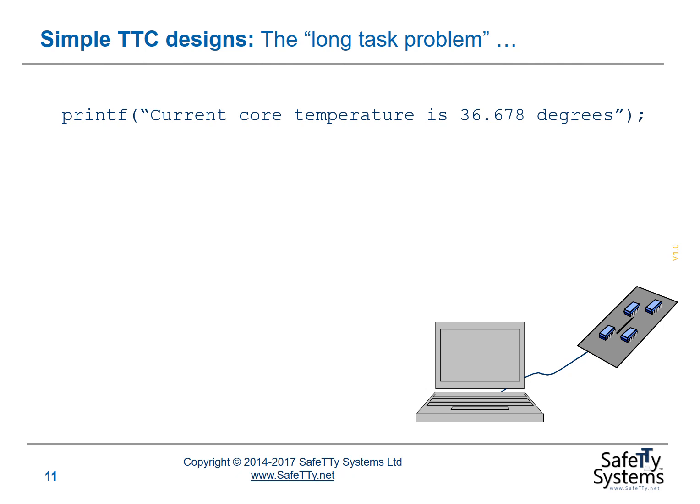So this is what I'm going to send. I'm going to use a printf function that is provided by my compiler manufacturer, I'm assuming, to send this string of characters to my laptop. My printf function probably looks something like this, where it writes the characters to a buffer within the UART hardware.